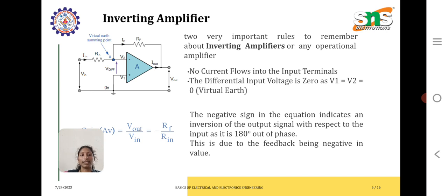The negative sign in the equation indicates an inversion of the output signal with respect to the input, as it is 180 degrees out of phase. This is due to the feedback being negative in value.